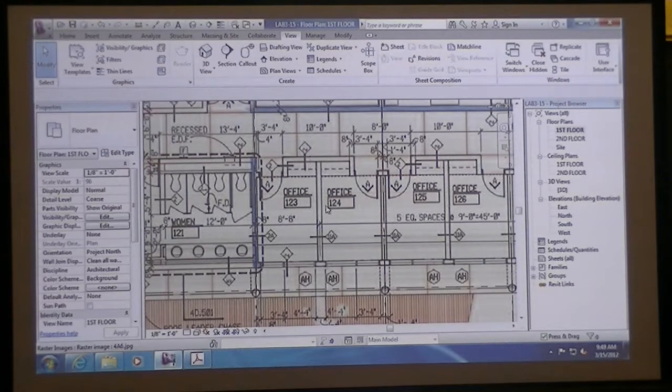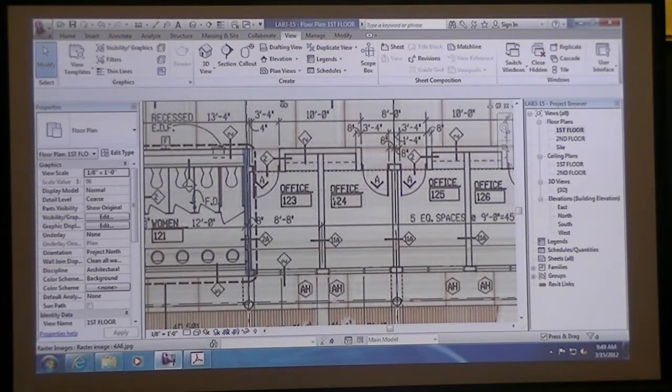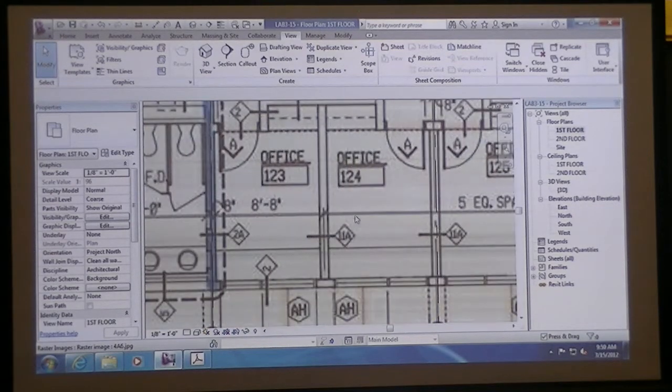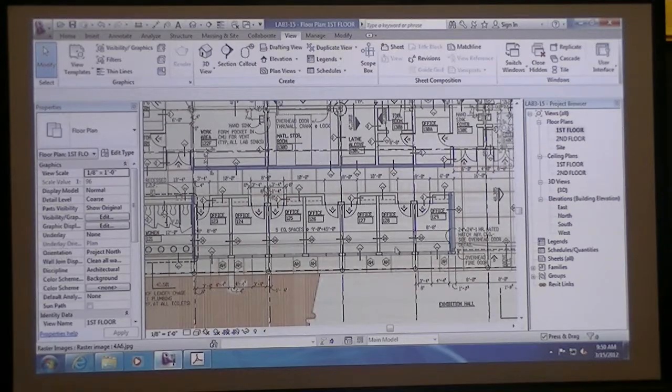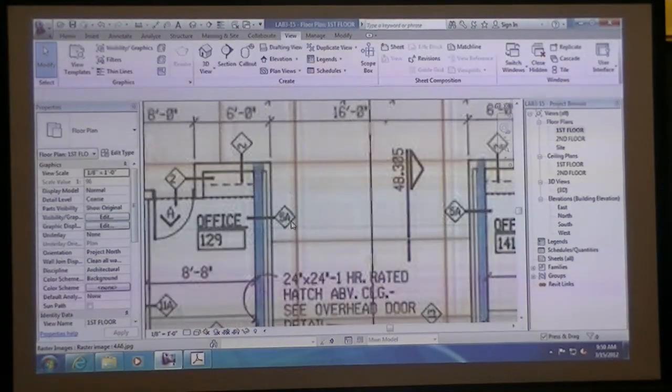So how do we know what type of wall we're supposed to be drawing? When you look at a set of construction documents, you'll see these tags with little diamonds. They might vary depending on who the architect is, but usually by default, and even Revit's default, you have these diamond tags and a little line that goes through the wall. That's indicating a wall type tag. This wall up towards the top here is a wall type 2. The one here in the middle is an 11A. If you zoom out, you'll see other walls around here, like another one, a 5A, and so on.